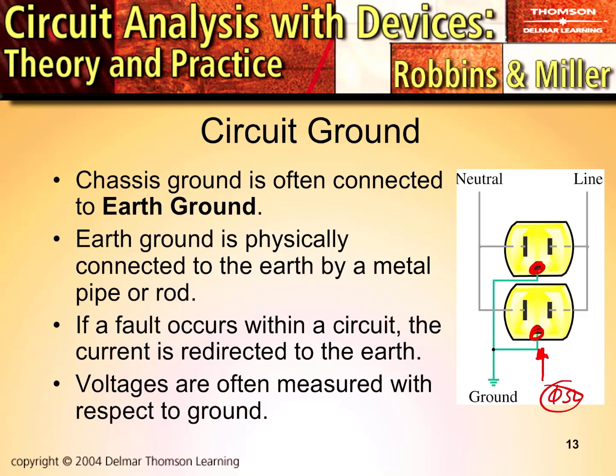And why is that? If we were to get an AC line voltage touching that chassis, we would immediately short the AC line to this protective ground, which finds its way back to the power system's source and shunts all the current away from you, and it should immediately trip the breaker or the overload protection.